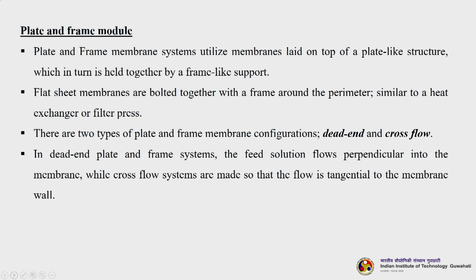Now, the next category is the plate and frame module. Plate and frame module membrane systems utilize membrane laid on top of a plate like structure, which in turn is held together by a frame like support. Flat sheet membranes are bolted together with a frame around the perimeter, similar to a heat exchanger or filter press. If you have seen the filter frame and filter press in the labs, usually it is shown in the mechanical operations lab.